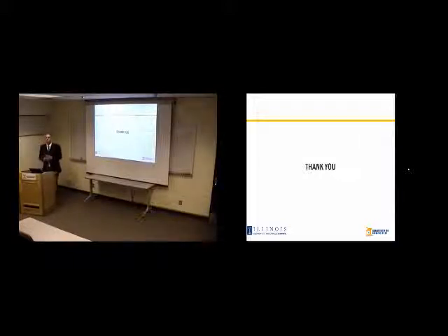The neat binder was a 64-22, if I remember correctly. The 3 modification types, the elastomeric polymer, the plastomeric polymer, and the ground tire rubber, were actually incorporated in a percentage to give the same PG grading for all 3 modified binders. Obviously increased from that of the neat. It did raise the high temperature grade, but they were consistent with one another.